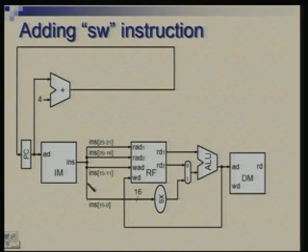So, now you see what is happening, that RS specified by this field would bring out some 32 bit number here, okay. 16 bit taken from here, sign extended, and we will control the multiplexer to select this path. Okay. When it is load or store, it is this path which will be selected. So, we must give input 1 to the multiplexer, control input 1, and for add subtract instructions we must give 0, so that this goes in.